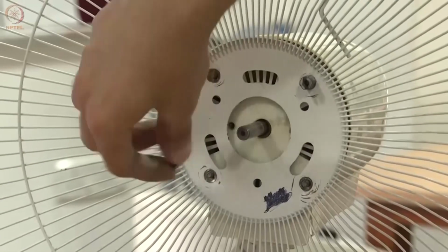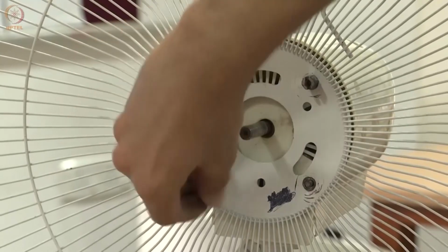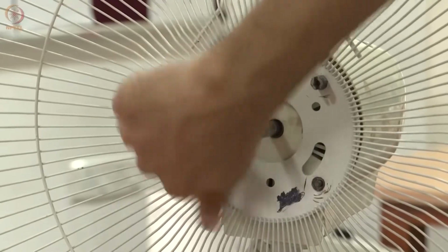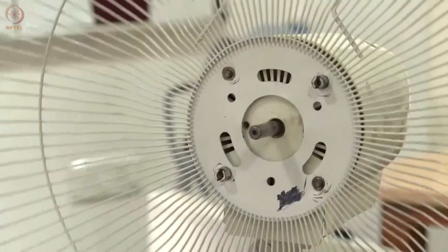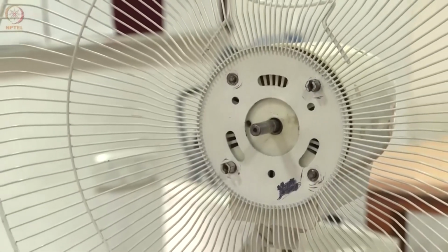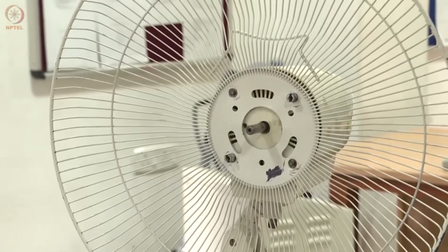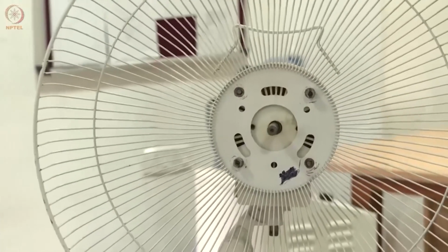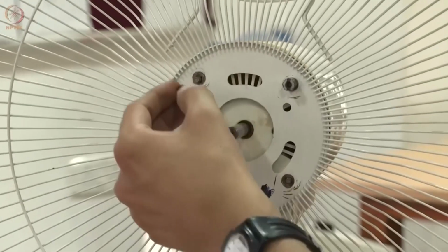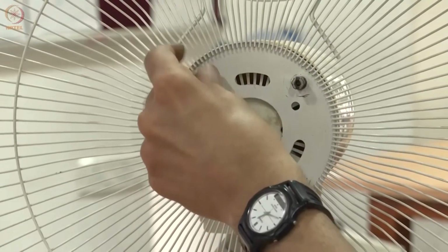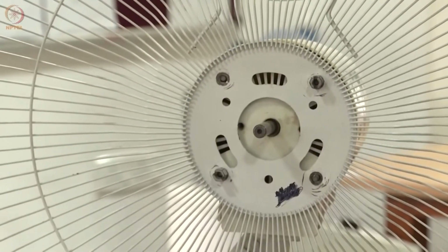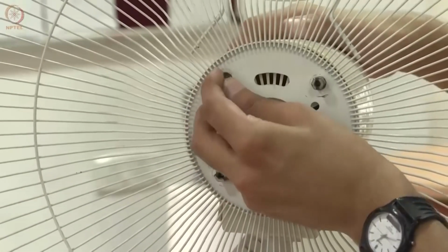Always put 2 diagonal screws first, so you get alignment first. Don't tighten them all the way, because you can see I've left some play in the system. I'll tell you why. Once we have 2 points, now the entire grill is constrained. Now you can proceed to tighten the other screws.